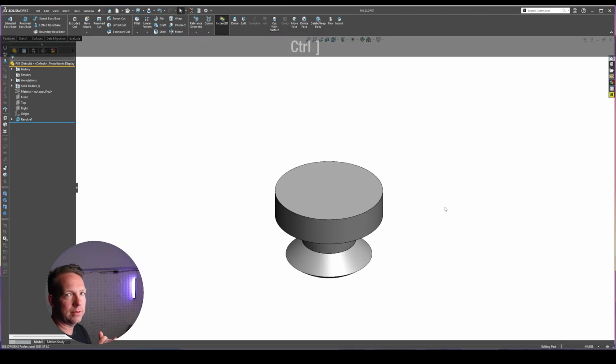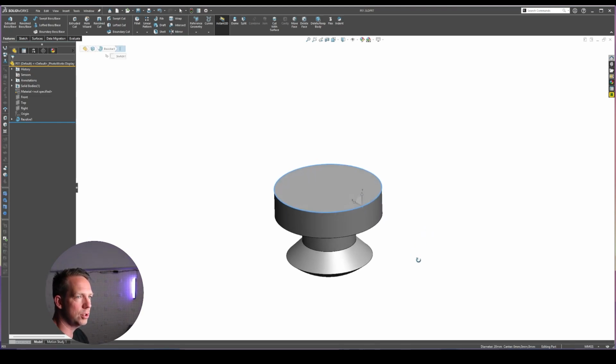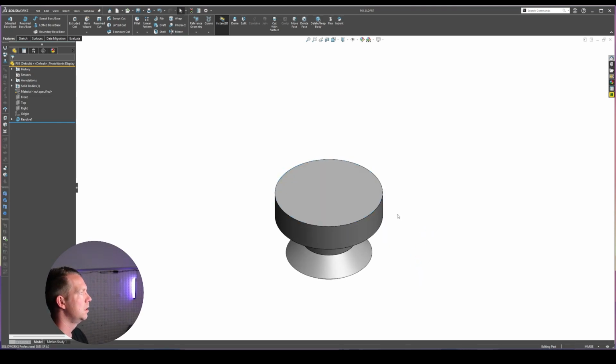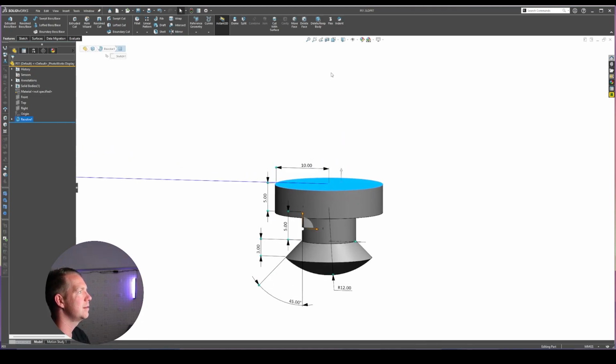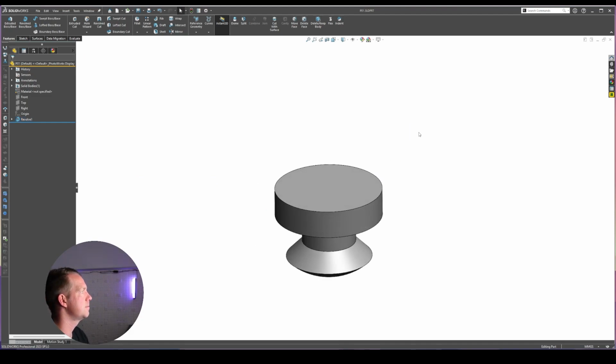All right, with that done, we're going to create some sketch profiles for our loft. We're going to have 3 profiles for our loft. One of those profiles is going to be this edge that's created by the geometry, and it's a circle. The next 2 profiles, we're going to create 2 planes, one above here and one a little bit higher, and we're going to sketch ellipses on those planes. So it's a good thing we've already used and learned about those tools.